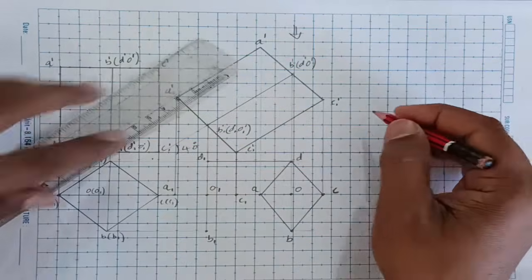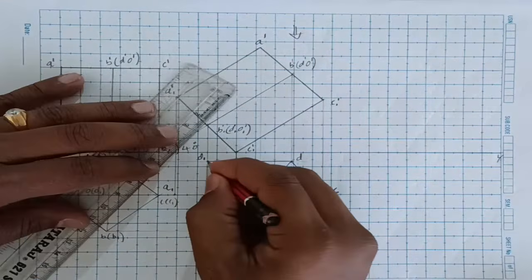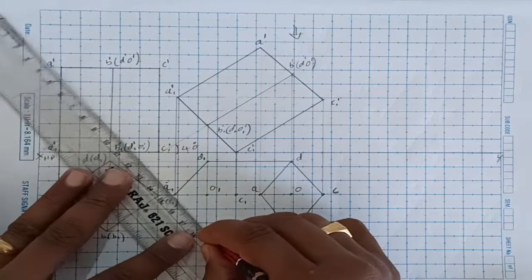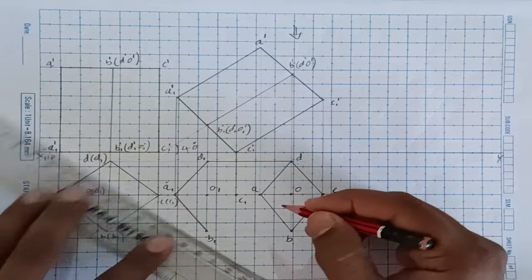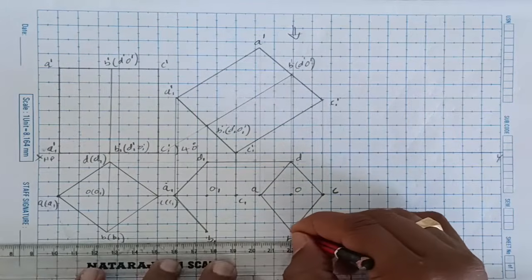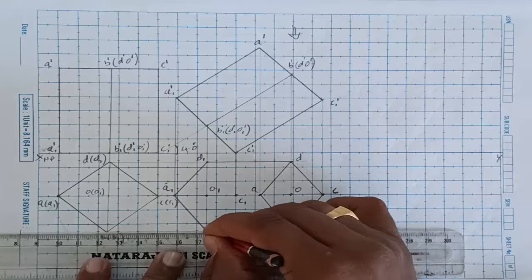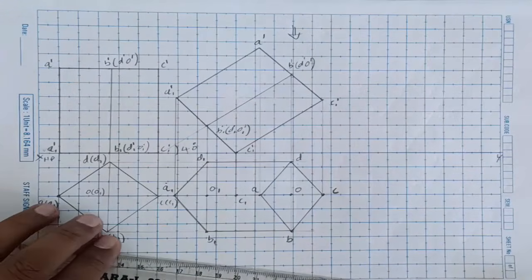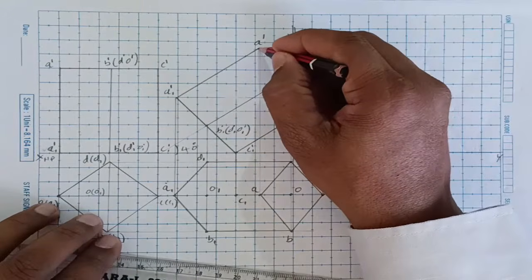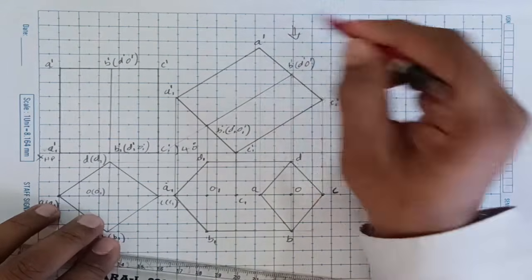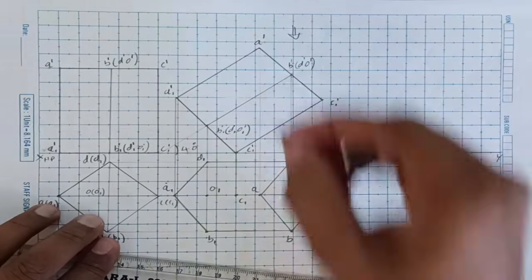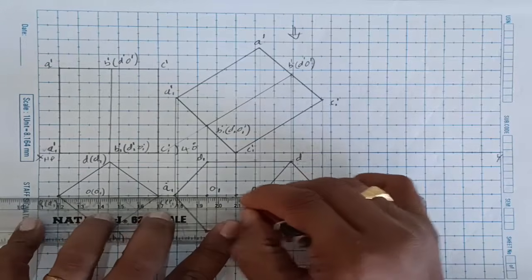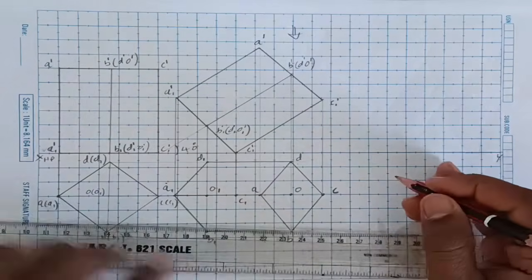Endmost points. And after that the next end point is A1, so that's why D1 to A1, end point. And the next end point is B1. The outmost points. A border means outmost points. Here after B1 the next is B. You can finish this border, outmost point. We need to make it visible first. And next check the first point, what is it? A dash. That means A to A1. This line will definitely be visible because it is coming first. That's why here also A to A1 we need to make it visible.